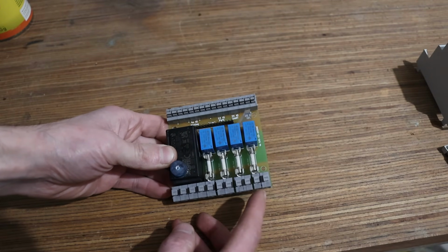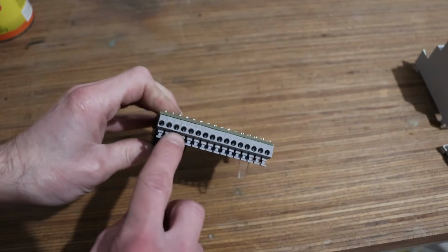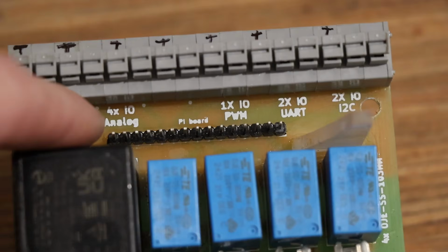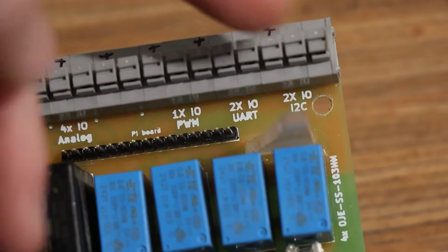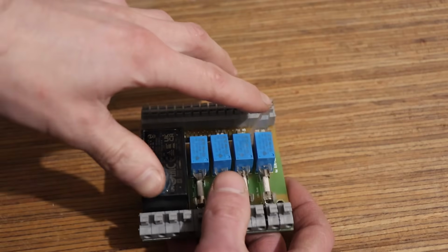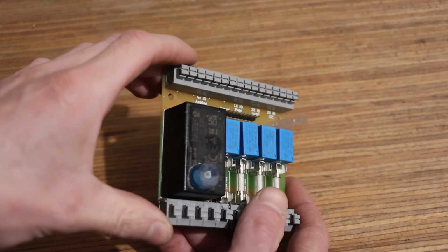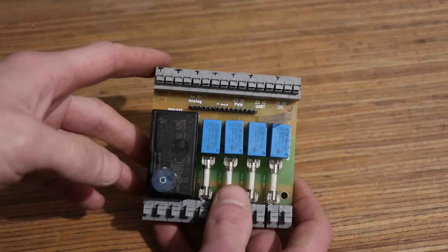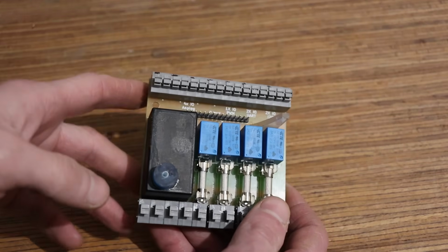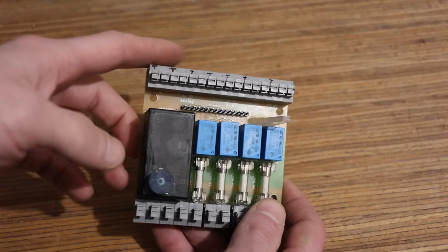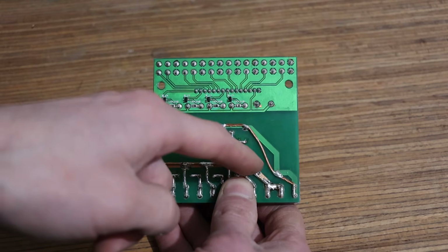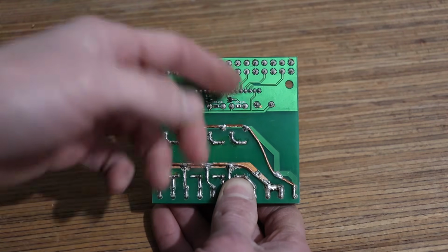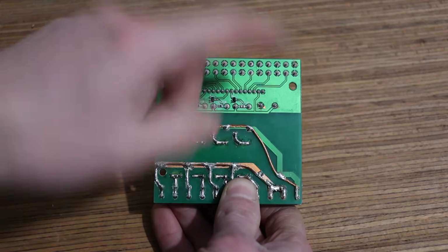It has 4 outputs and a bunch of GPIOs here: 4 digital and analog IOs, multiplexed. This is a PWM output, and there is some UART and I2C communication, also multiplexed with IOs. There are these 2 standoffs glued onto the components, which is not ideal. I probably will have to redesign this slightly for version 2, because I will probably need more of these in future. I could have made these bigger so they can carry more current and unmasked them so I can thin them, but instead I did this.